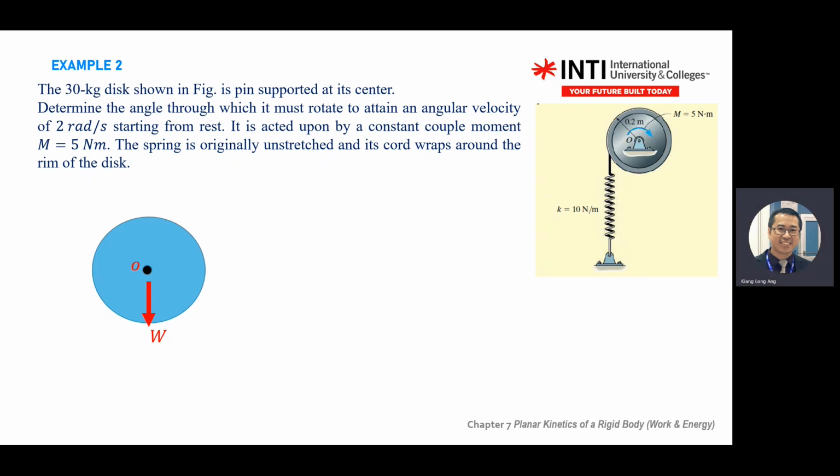One of you will forget your weight in your free body diagram, because you are so concentrated on external forces already. So don't forget. And this is pinned at O, so you have O, X, and Y. There's a force there. You'll be seeing pins in your coming assessment, so this one is automatic, you need to add inside your free body diagram. And there's an external moment M clockwise.